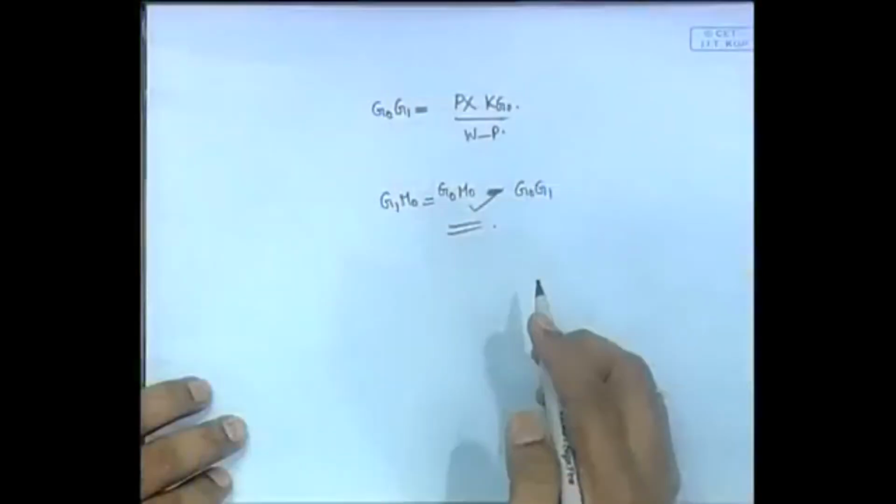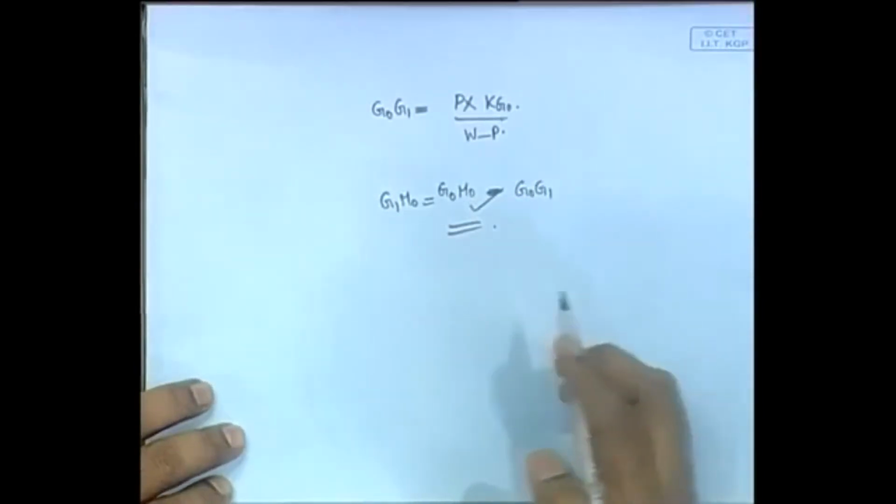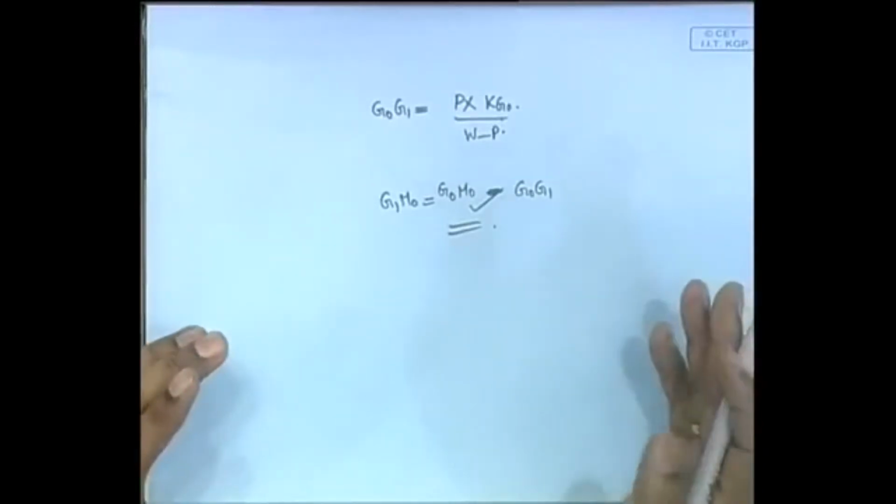You know the draft at the sea, okay. You need to find the draft aft and forward because of this. Okay. So, that is very simple again. You know what is the trim, P into x by MCTC. You can find the change of trim aft, small l by capital L into that trim T, that will give you your change of trim aft. Then similarly you can find the change of trim forward, then you find the bodily sinkage or bodily rise.